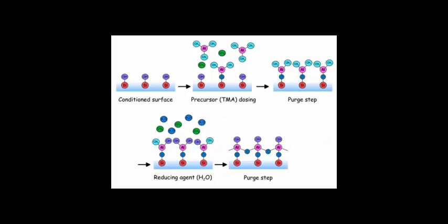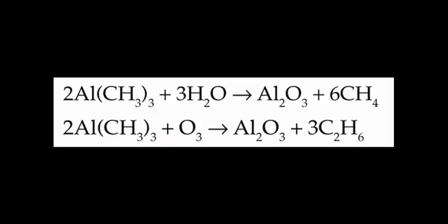One of the reactants which we use is trimethyl aluminum. In general, less than one monolayer of aluminum is formed at each ALD cycle. A simple explanation for this phenomenon can be offered based on the steric effect. That is, the TMA molecule is quite large and it is therefore not possible to position enough aluminum atoms on the surface in a single monolayer of TMA to yield a full monolayer of aluminum oxide for each cycle. We can only grow at most 0.2 monolayers of Al2O3 per cycle.